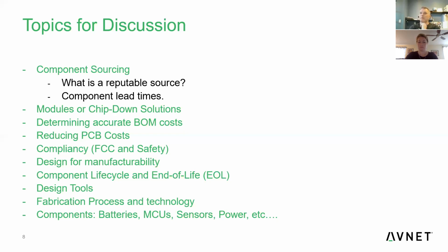So, even with the Bluetooth low energy product where it's pretty easy to do chip down, I still recommend that at least through the prototype phase, use a module. And then if that product is refined enough that you could move into a Kickstarter campaign with it, at least you're moving in with something that's not going to require a huge investment to get certified. And you can always worry about that certification and the cost reduction that comes along with the chip down solution later, right? Because I guarantee you're going to be looking for tons of ways to save money on the product, especially as you start to hit volume.